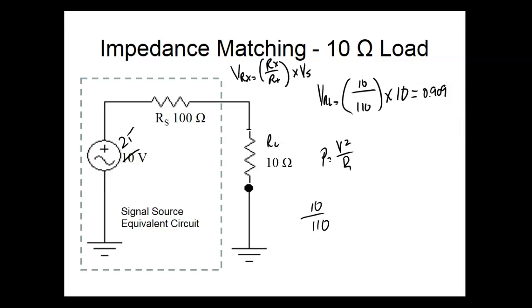Okay, now, let's keep that 0.9 down here. Then what you do is you pop it into this formula right here. So now we're going to use power is equal to V squared over R. We're not going to use I because that would add another calculation, right? You understand? So I'll step it through again.